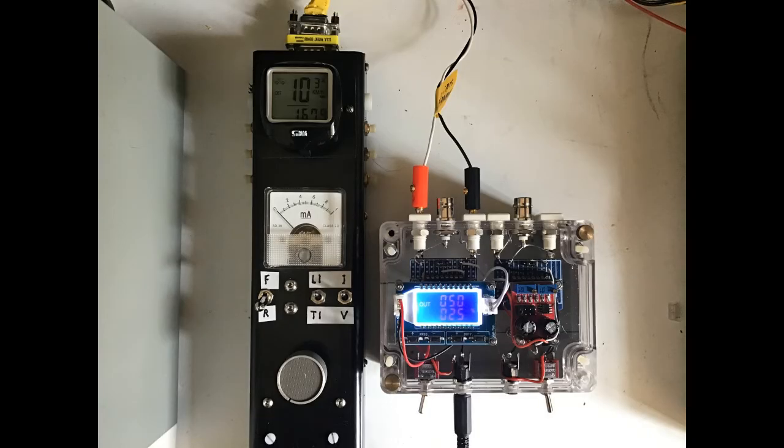This photo shows a simulation with a generated frequency of 50 Hz displaying correctly as 10 kilometers per hour. The pulse width modulating unit was set up at 25% to mimic the encoder.